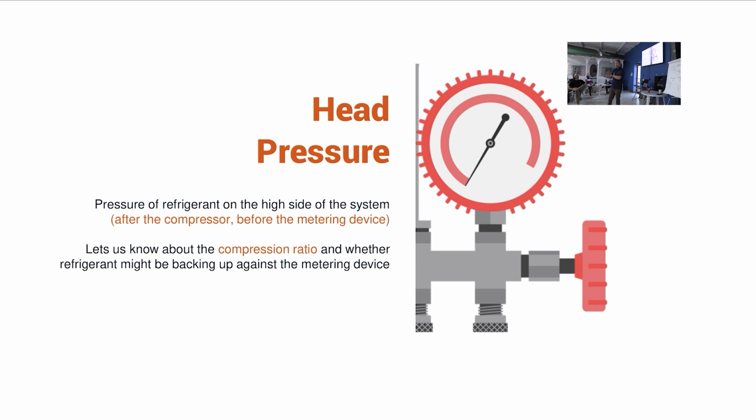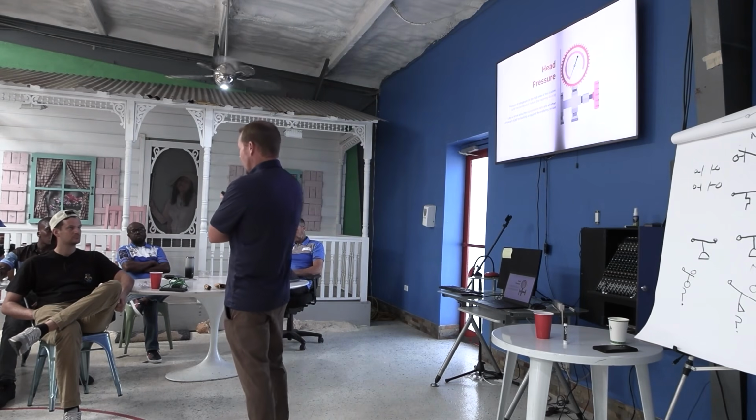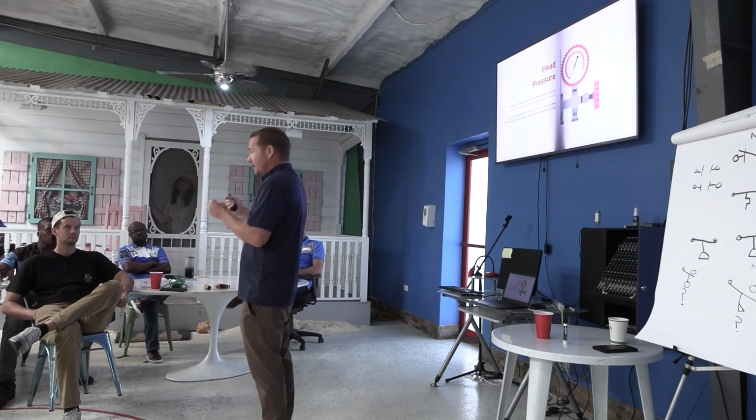Head pressure. So when I say head pressure in a residential context, what am I actually saying? Am I saying discharge pressure? I'm talking about liquid pressure, right? So I'm talking about liquid line pressure. So it's coming from that indoor unit, or going to the indoor unit. I'm talking about liquid line pressure. I'm not talking about discharge pressure. Those are not the same.